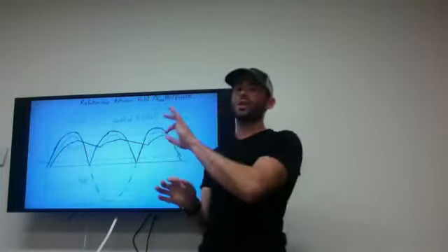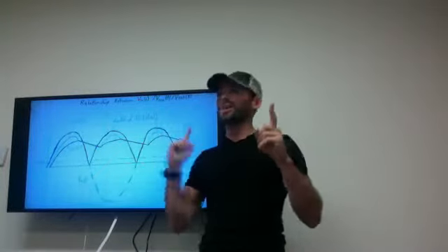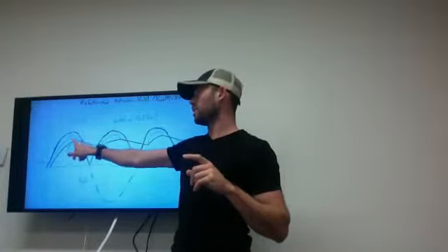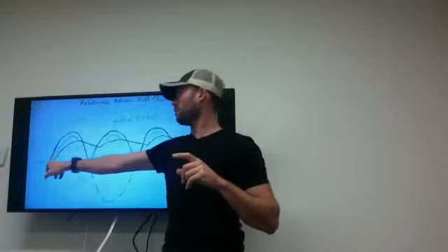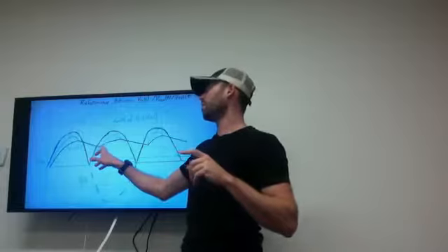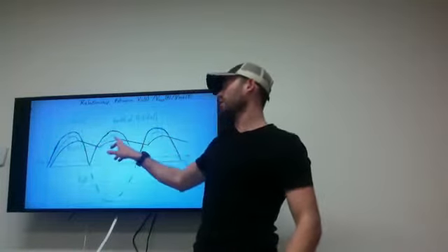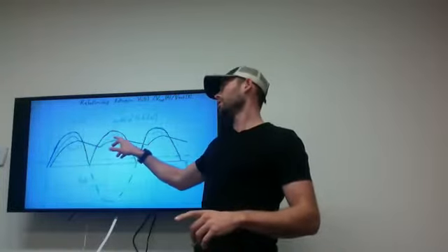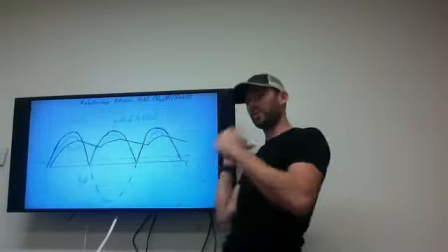At that point, there is no current going through R1, which means V out equals V rectifier. So these two graphs become the same voltage until we get to the corresponding VD on portion of the next period. At that point, we again have current going through that first resistor, which is why there's still that difference, and the same thing happens all the way through.